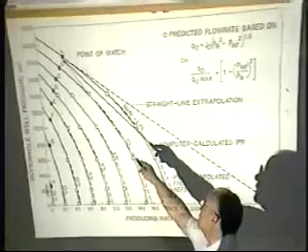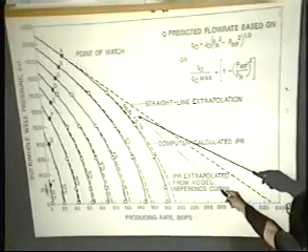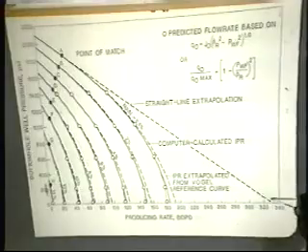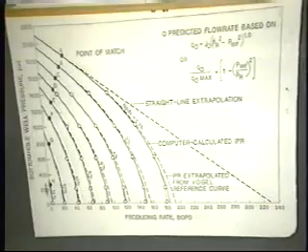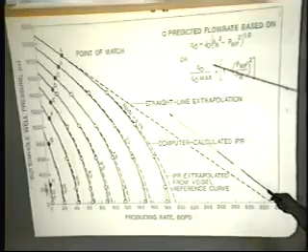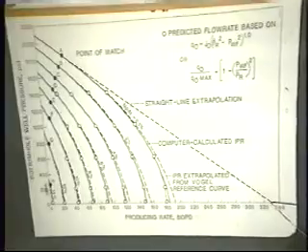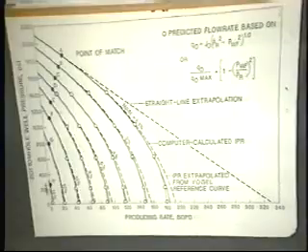And if you draw a line through match point A and continue as a straight line, this would be the productivity index expressed in terms of a difference in pressure, i.e. delta P. And you'd indicate that that well flowing at that rate, at whatever flowing pressure that is, has an absolute open flow potential of about 330 barrels of oil per day.